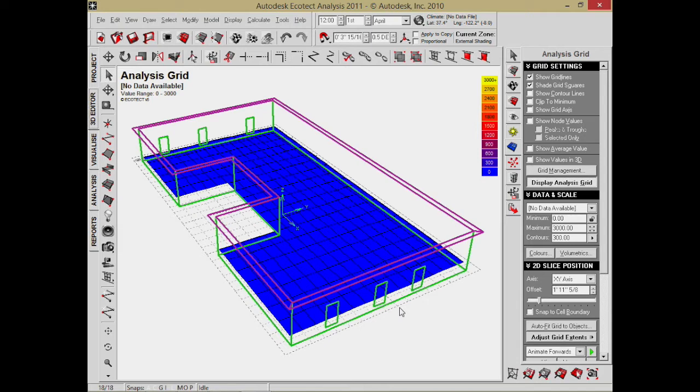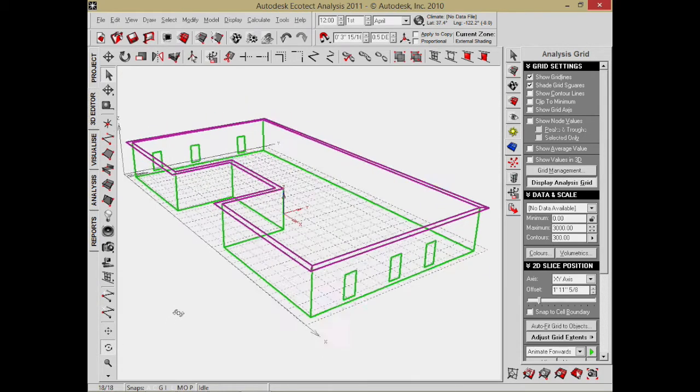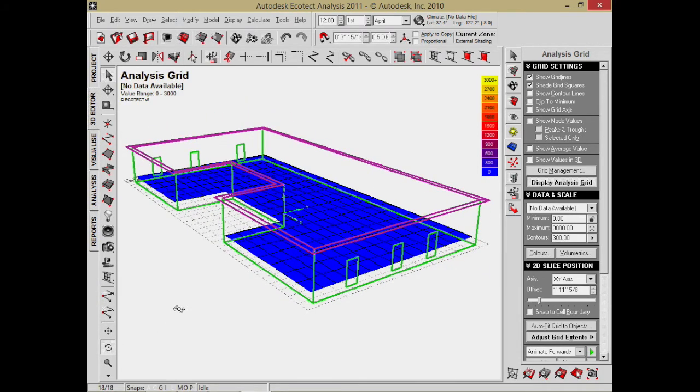Now, you'll notice the grid that's in there actually isn't exactly down on the floor. This is something we do from a daylighting analysis standpoint. When we compute daylighting for a building, we don't measure the floor. We measure almost 2 feet up. That's considered a desk height or some common working surface height. If you're in the metric system, it's typically 600 millimeters. So we put a plateau up a little bit higher because we're interested in the daylighting on that plane.